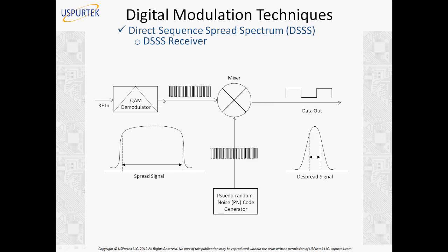Okay, there is a question here: how does it increase bandwidth by just multiplying with PN? Okay, let's go into a little more detail. If you take a Fourier transform of a low bit rate data signal, in the output you will see low frequency components. But a high bit rate data signal is actually a combination of high frequency components. High frequency components mean more bandwidth. You have more frequency components, ranging from low frequencies to all the higher frequencies.